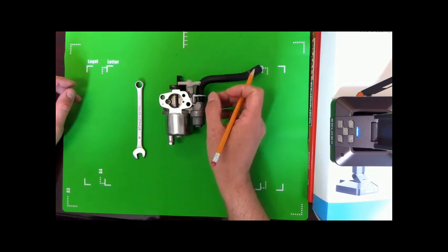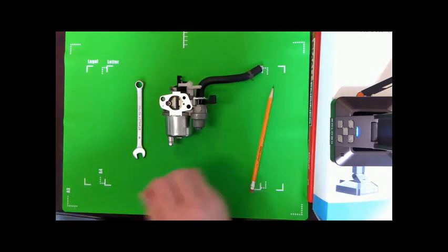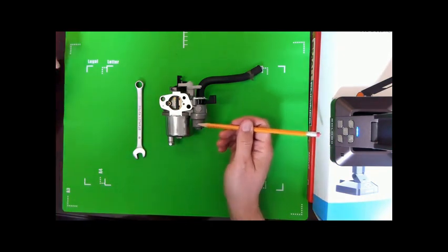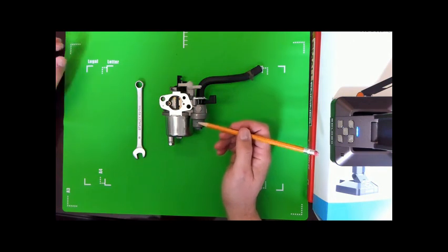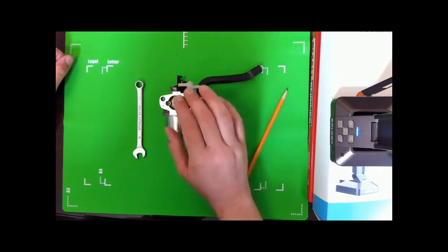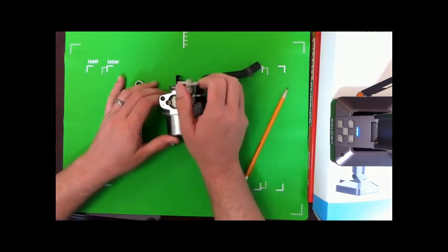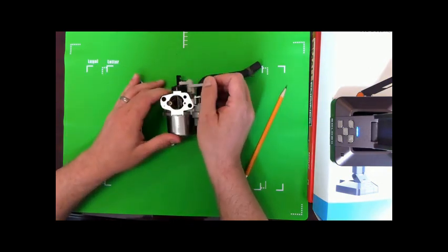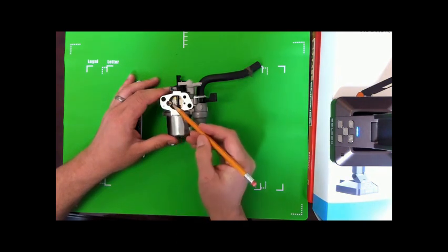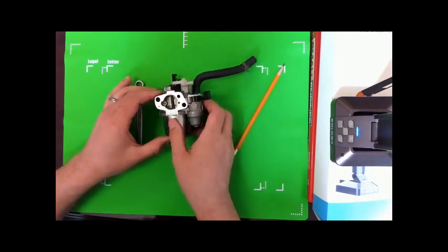This is associated with the fuel shutoff lever. We can actually turn the fuel off if we want to run this carburetor out of fuel after we're finished mowing or running our generator or what have you, instead of having to drain the entire tank. You're looking at the choke side here, our choke lever, and that's the choke plate that you can see moving in there. Some people will call that a butterfly, but we're going to call it the choke plate right now. You should be able to see right here, brass here and here, those are two of our jets that we'll get to in a minute.